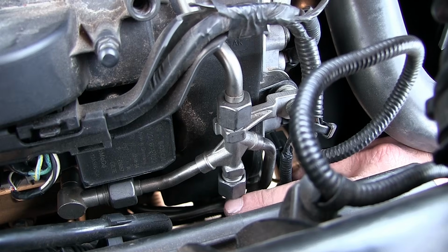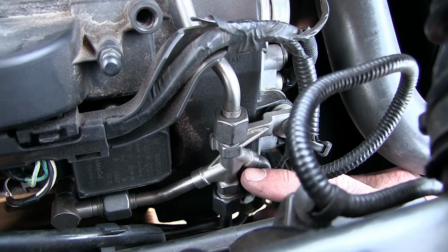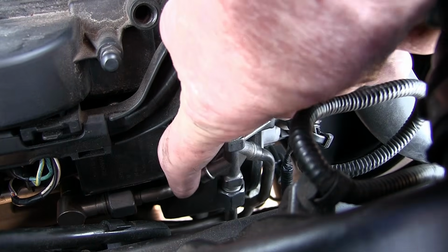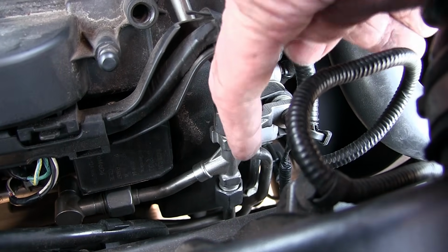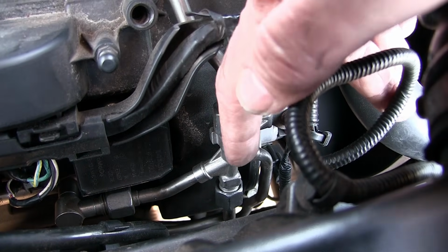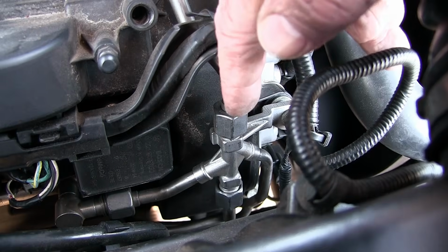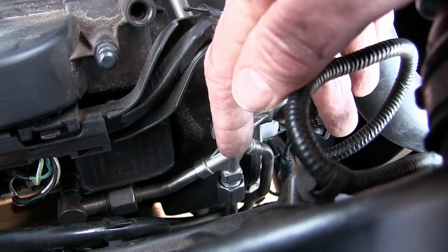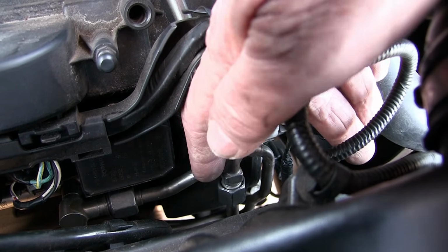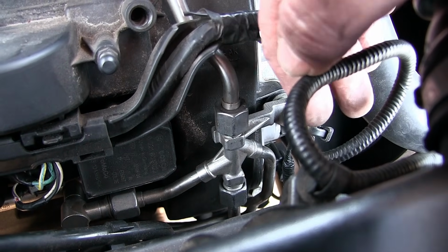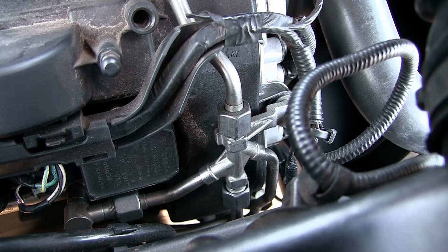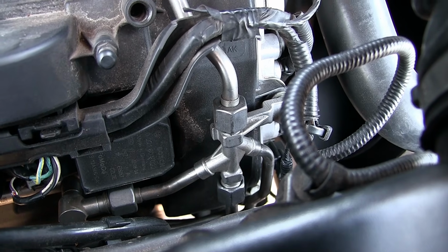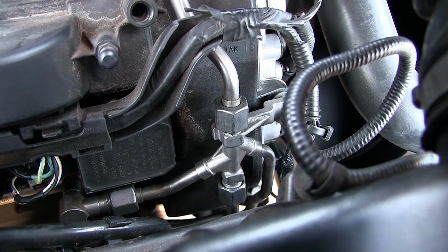This line down here comes off the number 1 pump. So what I want you to notice is how this line right here angles back down and this line goes straight across. Well, the reason that 2 doesn't have as big a problem is because it's going straight across and the volume is easier to push straight through rather than make a sharp or a tight angle to go back down. So even though bank 1 appeared to be the problem, both banks really have the problem, but the reason is because of the type of connection that's right here.